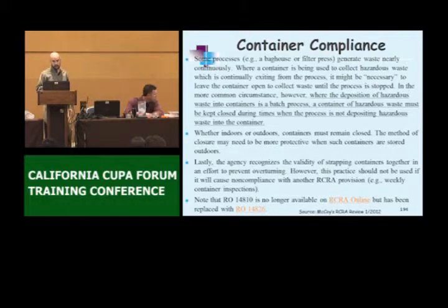So container compliance, let's see. Where it's a batch process, this kind of talks to that. These are the questions that came up from the original memo. A container of hazardous waste must be kept closed during the times that the process is not depositing the hazardous waste. But when it is, again, if it's adding to a container, you're fine. Whether indoors or outdoors, containers must remain closed. That was a question that came up. The method of closure may need to be more protective if outside. That's kind of common sense. And just a best management practice too.